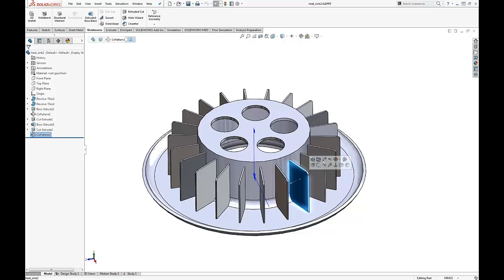And of course, I don't have a trivial solution, because, for example, if I'm putting too many fins, they are blocking the flow of the air. If they are too few, they are not dissipating. So it's not trivial. And of course also the geometry is not trivial. So what I can do, I can just have from the sketch of the single, you can see here.